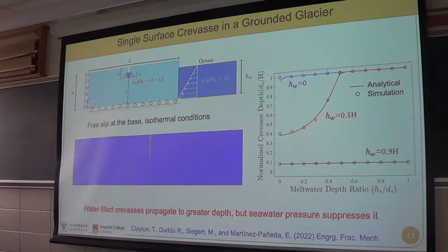And so we get these analytical solutions, and then for each of those cases, for a different water height in the crack, we run a phase field simulation. That means each of these points is a phase field simulation that we ran. And then you see how it perfectly matches with this analytical solution. So that's when we said that, okay, first of all, this verifies that the phase field model that we set up actually works.